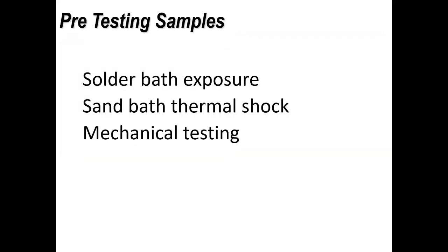Now, one of the other things that we do sometimes with samples is to do some stress. So if you take a sample, be it a PCB, an assembly, a solder joint, we may well stress it before doing microsectioning. And the idea is to show up what changes might have occurred. Is the sample possibly going to get worse by itself? It's not going to get better by itself, and how bad that might be.